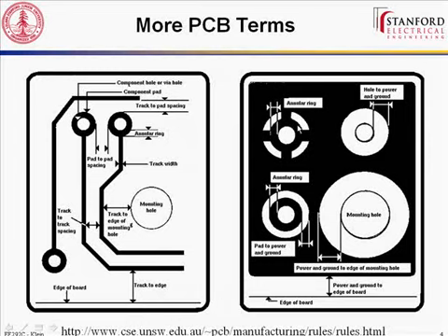Now, one thing that you'll notice on these inner layers is that, for example, right here we have one hole, and there's copper right around the hole, and then there's a big gap, and then there's the plane. So this would be a via or a component hole that goes through the plane layer but does not connect to it electrically. You still have to have this copper around the actual drill so that they can plate the hole later on, but it doesn't actually connect through. So you'll notice that means there's quite a large space here that you cannot use in this plane layer between vias or between component holes.